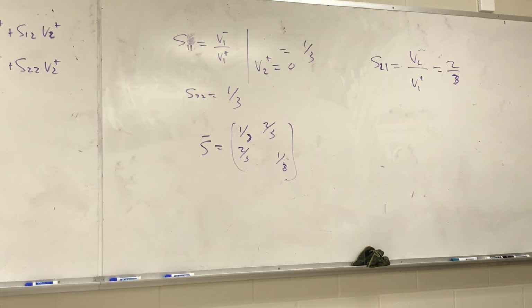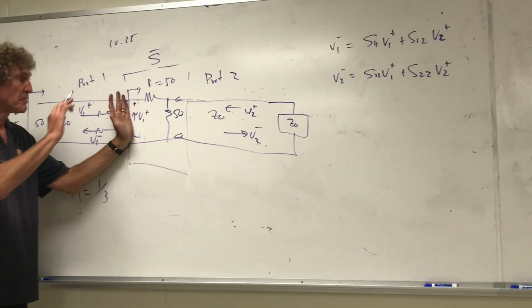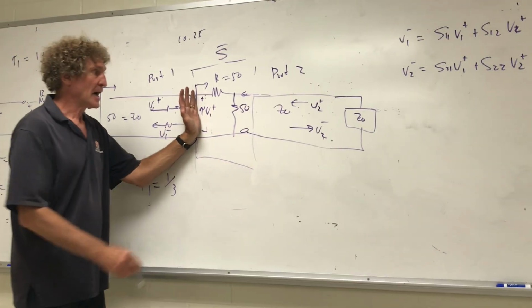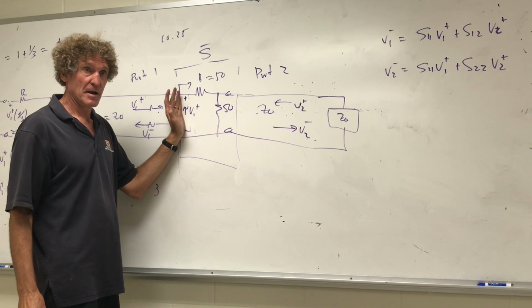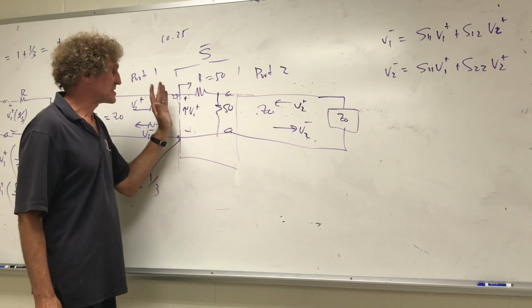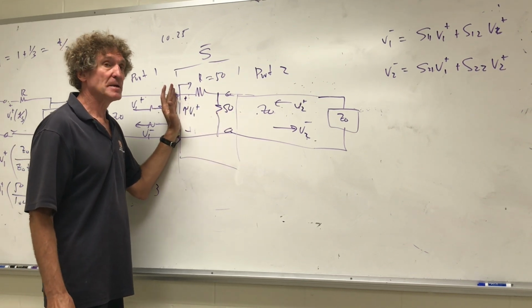Now, if he puts a resistor here, and I'm going to talk my way through this. I want you guys to, if this is 50 ohms, here's what changes. Please listen. Now my input impedance here changes. I have 50 in parallel with 50, which is going to be 25, right? 25 plus 50 is 75. Now my input impedance is 75.